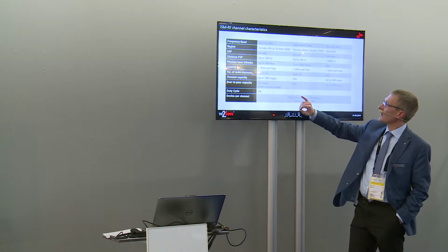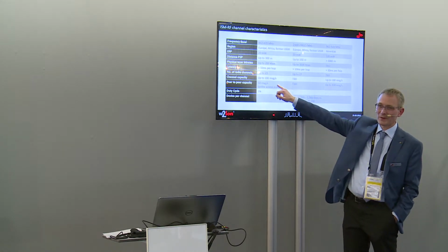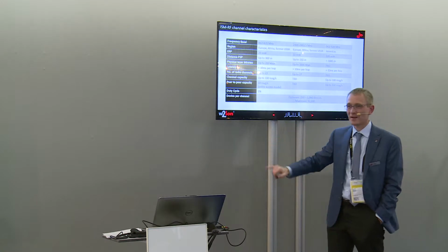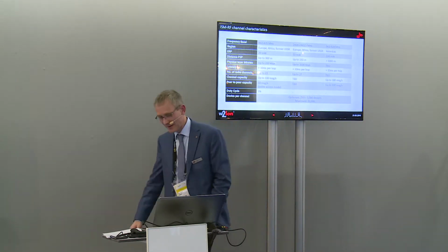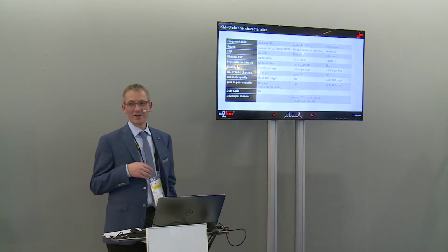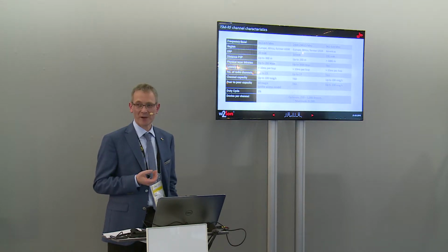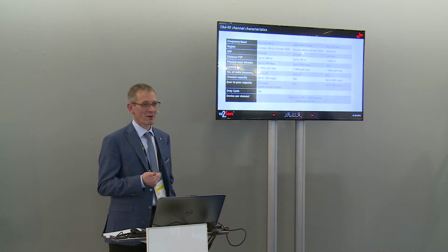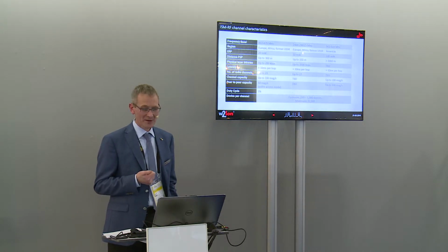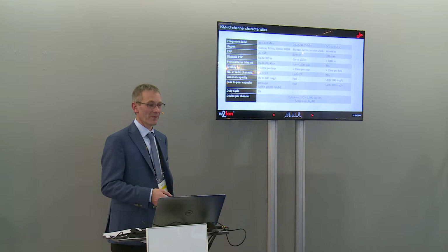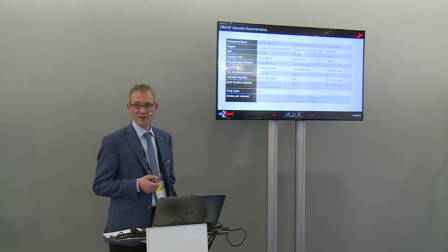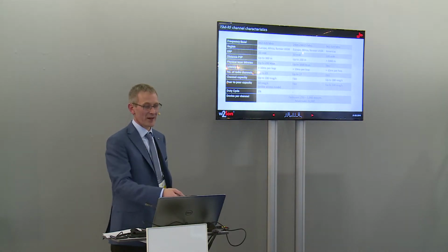With the tests that we have run so far, we were at 10 messages per second. That does not sound like a lot, and the reason for this is the regulations we have to comply with in Europe. There's the polite access mode, which allows a single device to transmit a message only every 100 milliseconds. So one message every 100 milliseconds. That's quite an obstacle for this. But this only applies to the short-range devices in the 863 to 870 megahertz band.